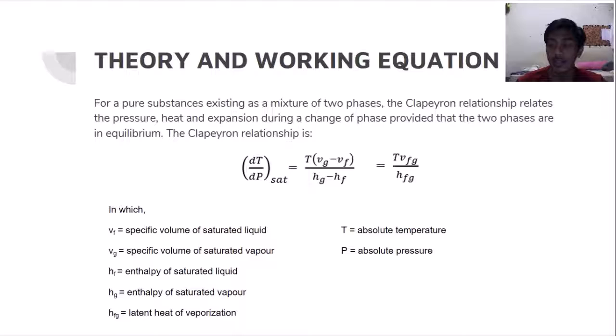The water inside the boiler is heated up by the electrical resistance and starts to evaporate. As more water changes phase from liquid to vapor, more vapor accumulates inside the boiler vessel and increases the pressure imposed on the water surface. This pressure build-up tends to increase the resistance faced by liquid molecules as they change into vapor, consequently increasing the saturation pressure of the remaining liquid.